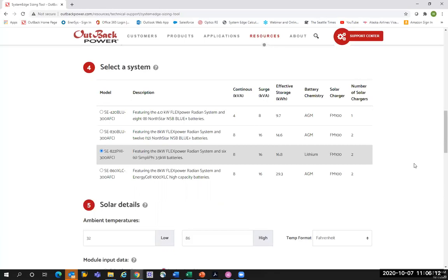But getting back to the surge factor, ever since they came out with high efficiency motors at the turn of the millennium, they actually have more surge current, because what's called the slip between the magnetic field and the current is much tighter and makes them more efficient, but they also have higher inrush current. And really a soft start is the best way to go if you want to minimize that. I think it's the most cost-effective way to do it and most reliable. A variable frequency drive, you can do the same thing.